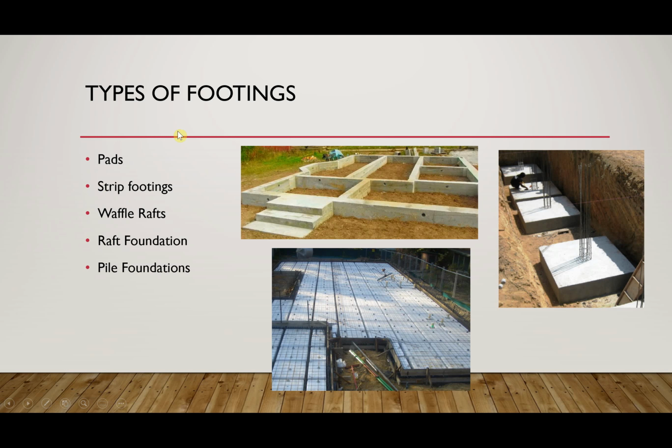Our strip footings. So the strip footings are these ones here. They're starting not to be used as much anymore in Australia. These would be located under the walls of the house, and then your floor would just span between them. Waffle rafts are becoming more and more popular.